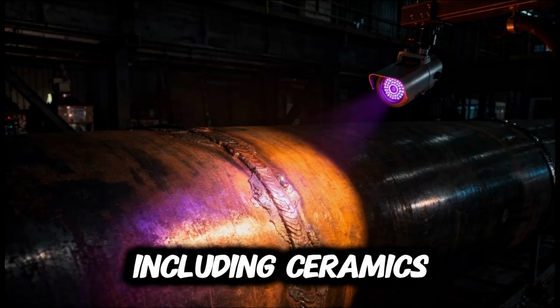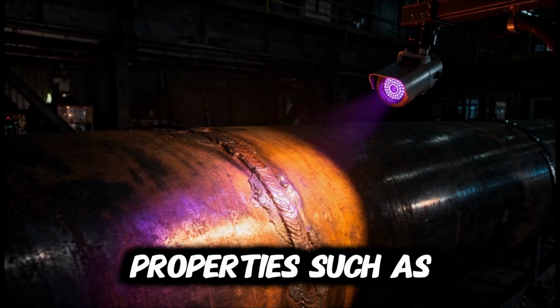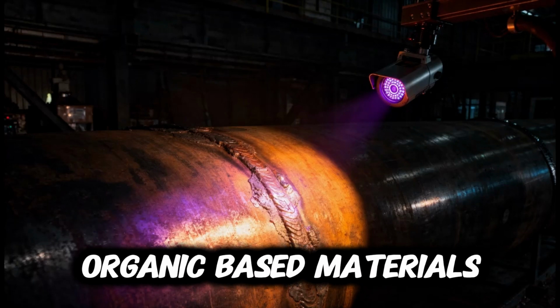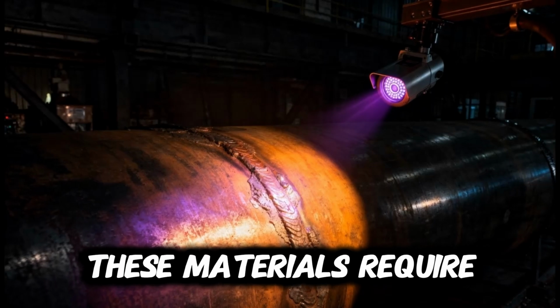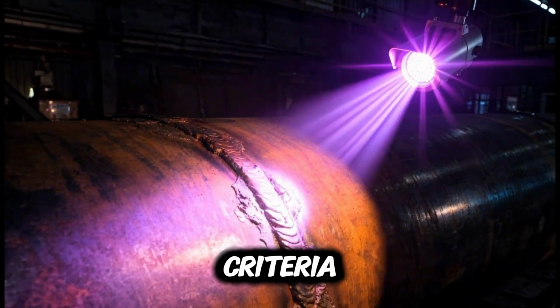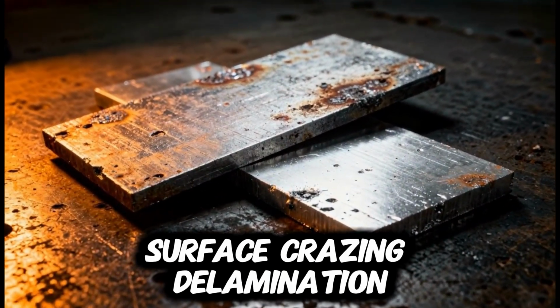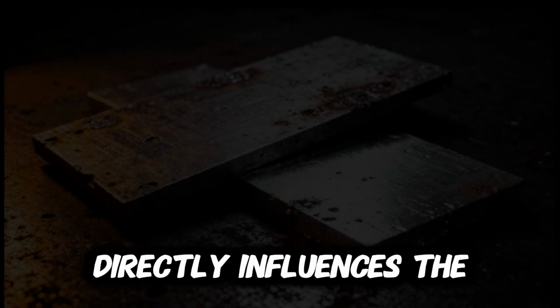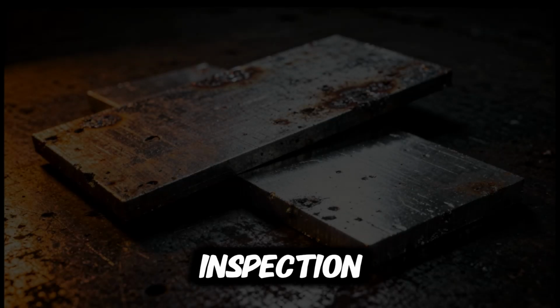Mineral-based materials, including ceramics, glasses, and refractory compounds, display distinct optical properties such as translucency, crystalline fracture patterns, or thermal shock damage. Organic-based materials encompass polymers, elastomers, adhesives, and composite matrices. These materials require different visual evaluation criteria, including color change due to UV exposure, surface crazing, delamination, blistering from chemical attack, or fiber exposure in reinforced composites. Correct material classification directly influences the selection of illumination type, magnification level, and acceptance criteria during inspection.